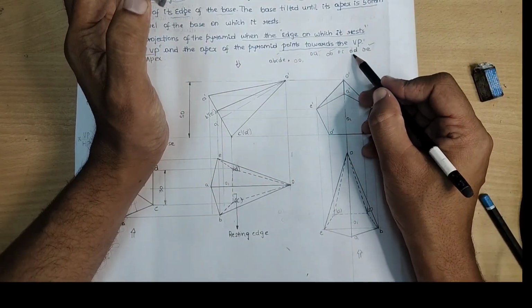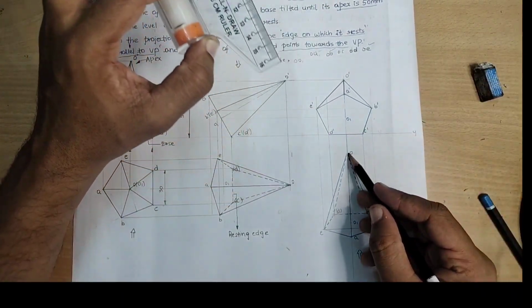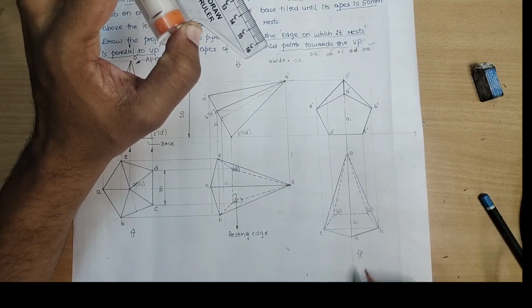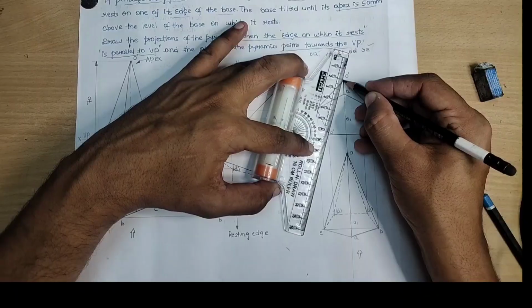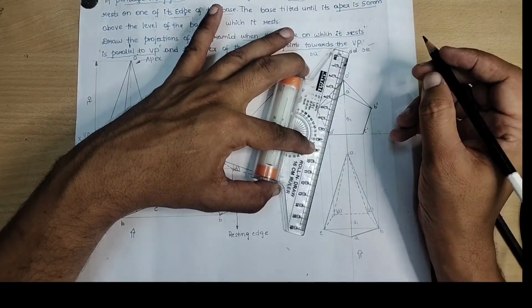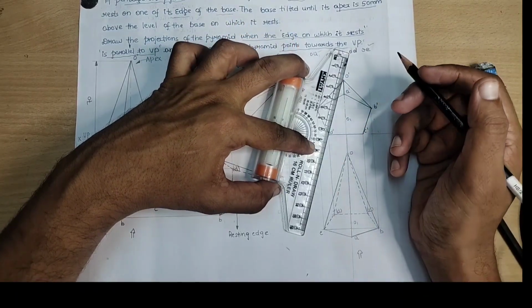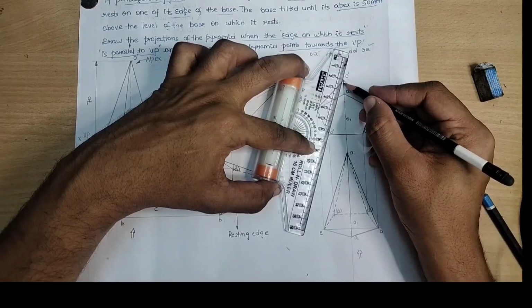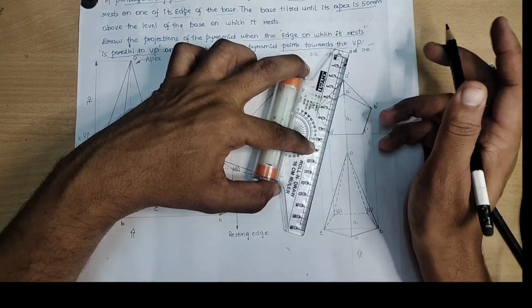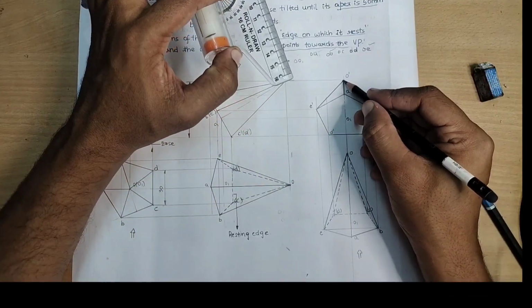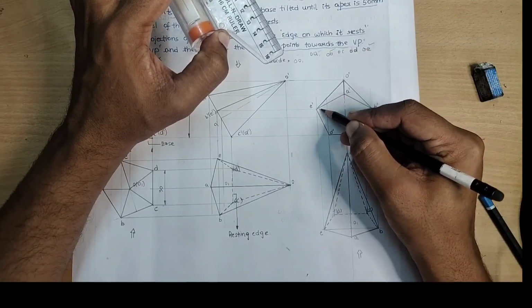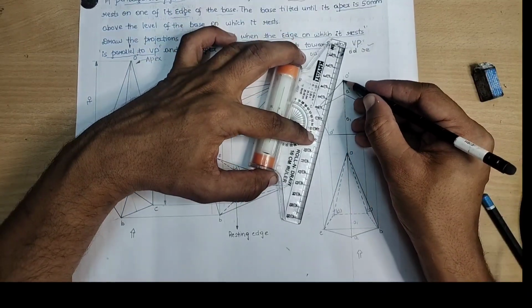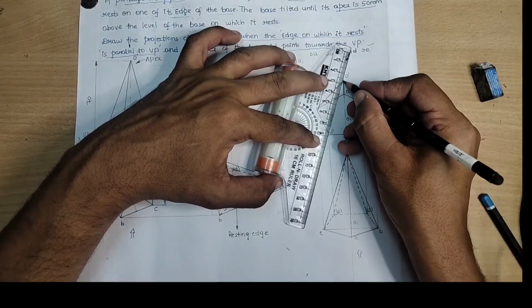The last ones are O to C and O to D. O point is here, C point is here. Don't you think it is far away from the observer? So O to C and O to D become invisible. I will let you know one more rule. Take a note towards the side of the paper. No two lines will be the same. Whenever you are drawing a line from O to D, it is crossing the visible line and moving, hence this should become invisible.